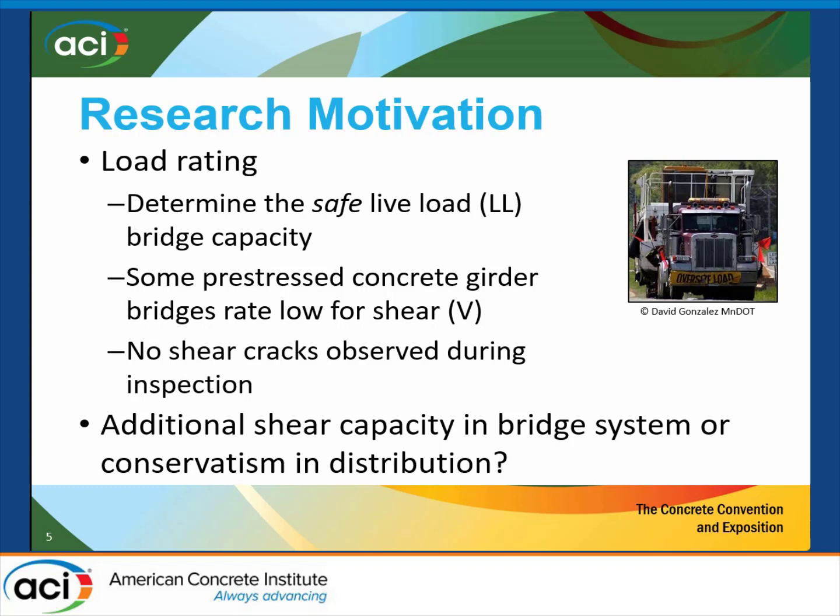But if you go in and look at these prestressed girder bridges, there's not a lot of cracking. There's really none observed during inspection. And for the most part, the bridges aren't falling down. That would be in the national news. So something is disconnected here. One of the main questions is: is there some additional shear capacity in the system, specifically in the girders, or is there some conservatism or disconnect in the way that we're distributing the load from the traffic to the individual beams? So kind of a two-part question.